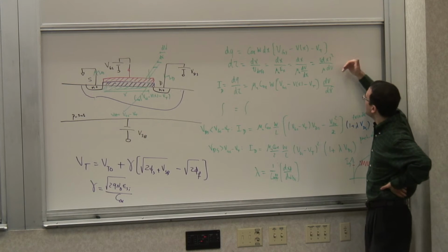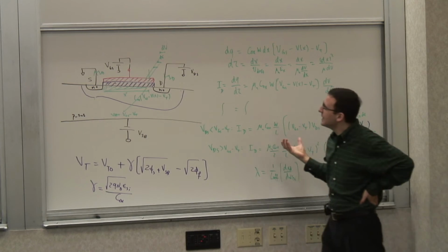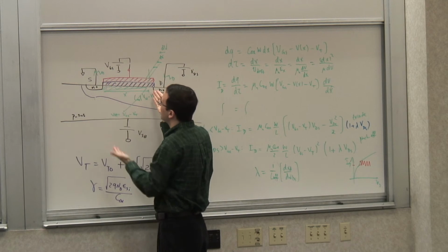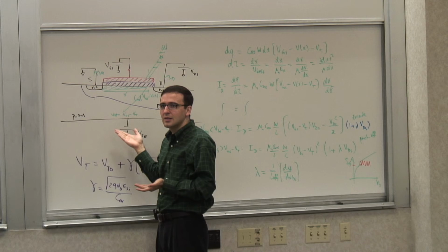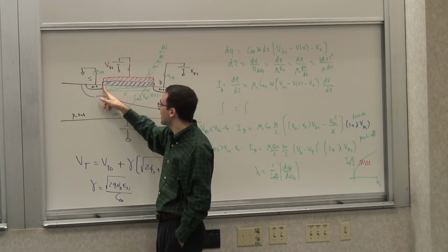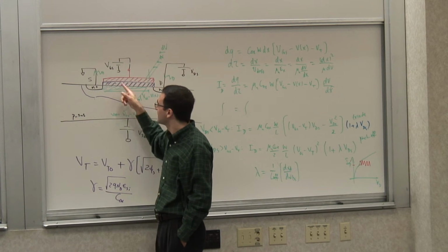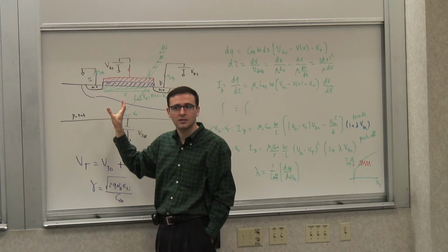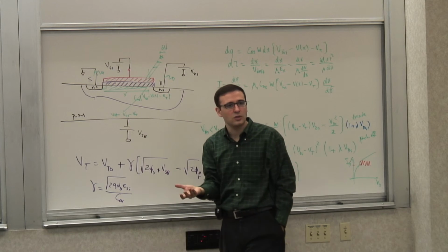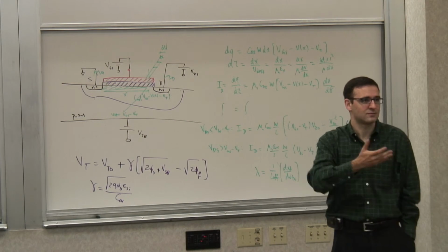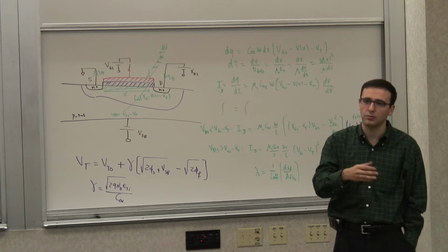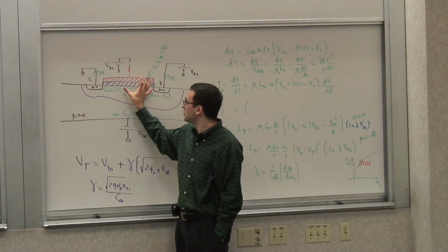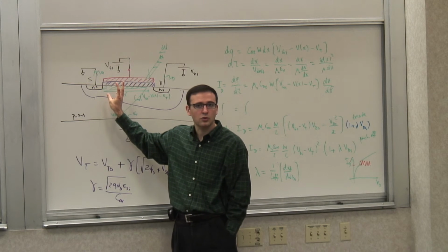So we look at this and see what it depends on. Really, on the first order, what does it depend on? So let's say the charge distribution is kind of uniform. If the charge distribution was uniform, the time it takes for an average electron to get from here to there is what? It's the channel length L divided by the drift velocity, right? So if you want to make this faster, what can you do? The drift velocity is kind of determined by the electric field and all those things, so you can apply a larger field but up to a certain point, right? But one of the easy things you could do, at least on the surface, is to make the channel length shorter and shorter.